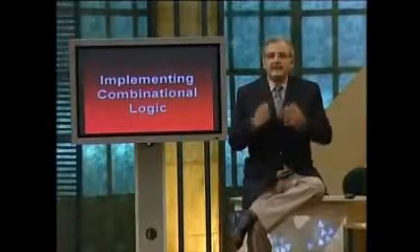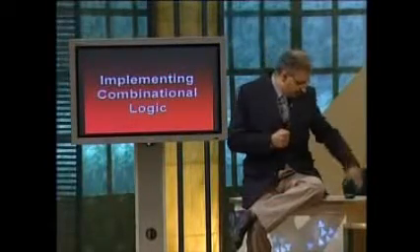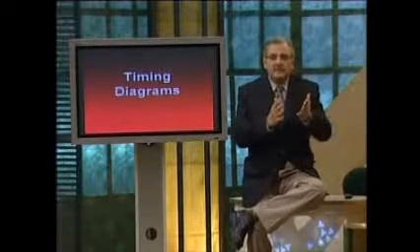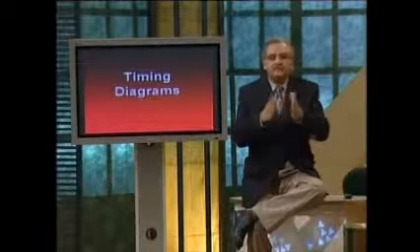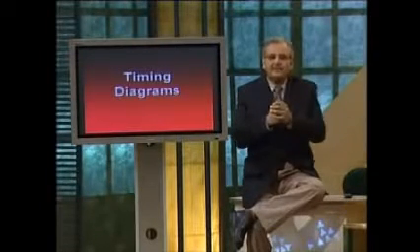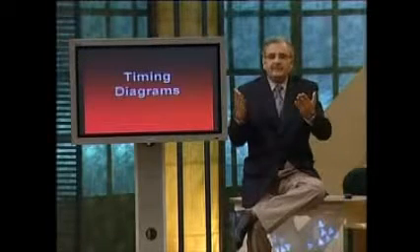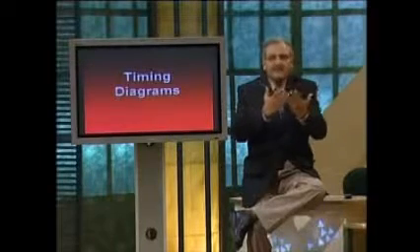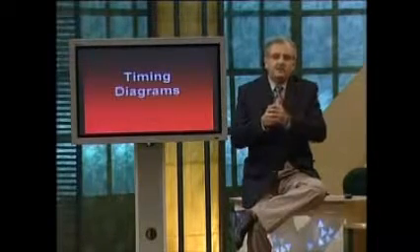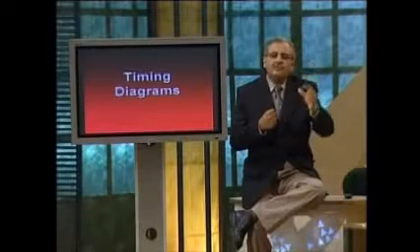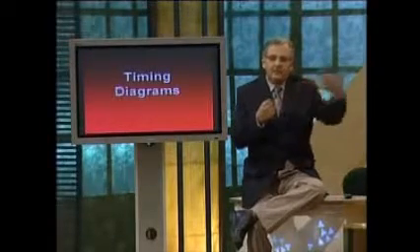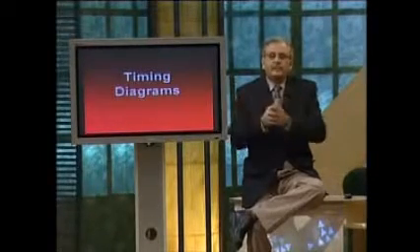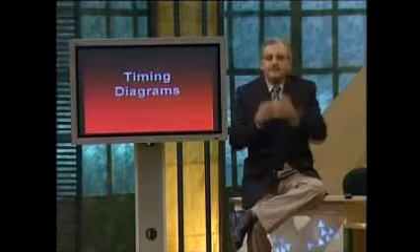We have just looked at the timing diagram of the adjacent ones detector circuit. As we saw, we can represent all the inputs and the output and the outputs of different gates within the circuit through a timing diagram. For different time intervals, we can see the different outputs, the intermediate outputs and the inputs, and we can verify the operation of the circuit. The other thing we saw in this diagram was that we used the product of sum implementation of the circuit, and we applied the different inputs, and we determined that the product of sum circuit does give you the appropriate output. So it is equivalent to a sum of product circuit.